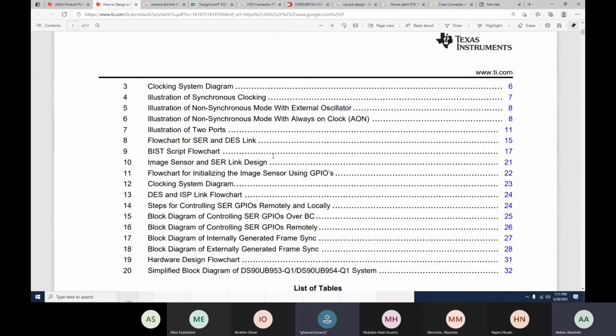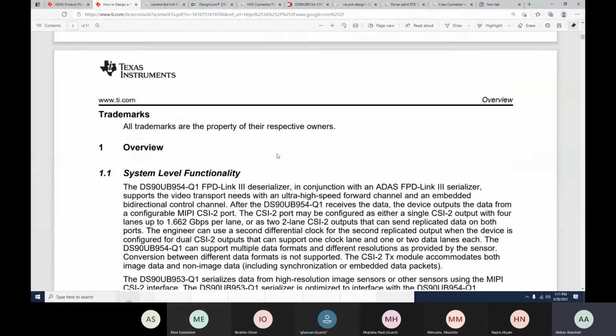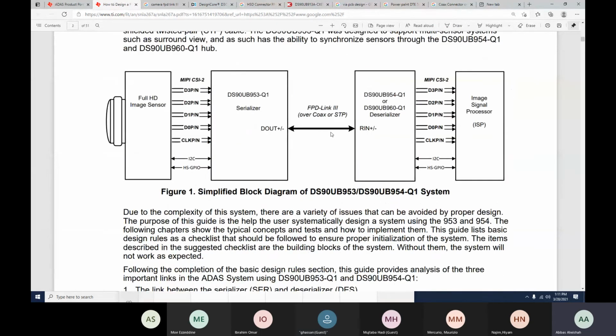Yes, so you hit on a very important point in terms of the industrial application, right? Like if you're making 1 million of these, you look at it and you say, okay, I have less than 1 meter, but this is cleaner because this separates every pin. You don't need an extra filter. Coax, the cable is cheaper, right? The cable is cheaper than shielded twisted pair, and you're making 1 million cars that use this camera,